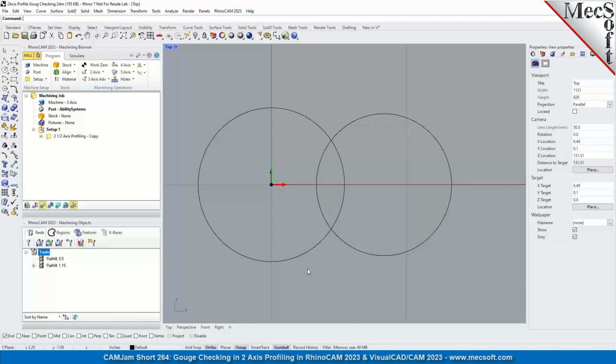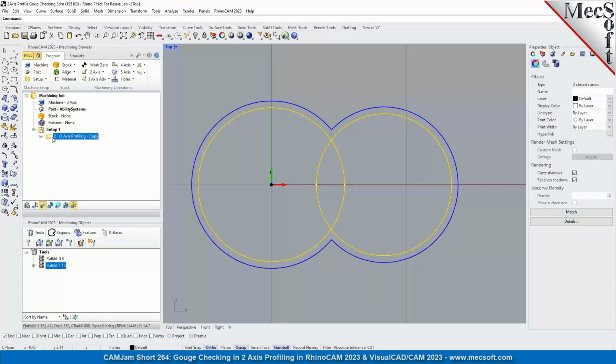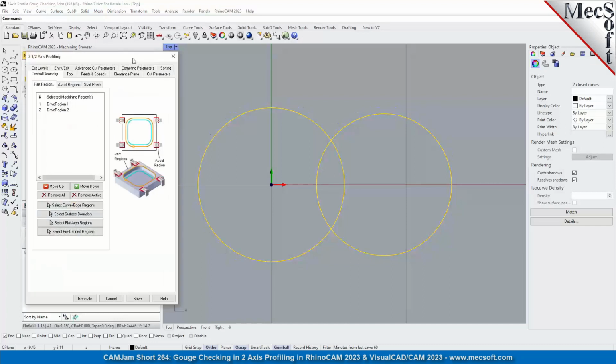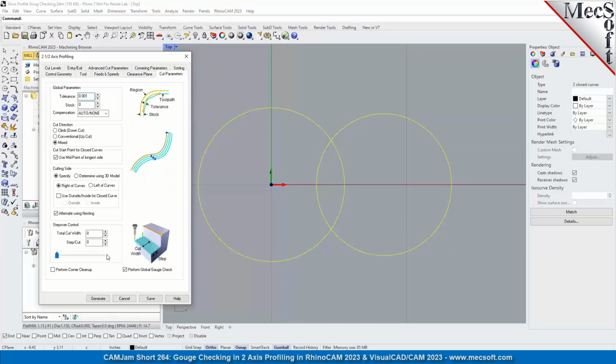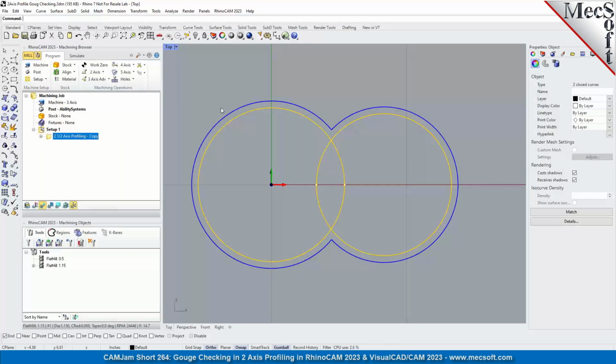And if you have perimeter curves and some are overlapping and some are not, they don't even have to touch. You just select the curves, and let's go into the dialog right here. All you gotta do is check this option here, perform gouge checking. And what it'll do is calculate the perimeter of those curves without violating any other curves.